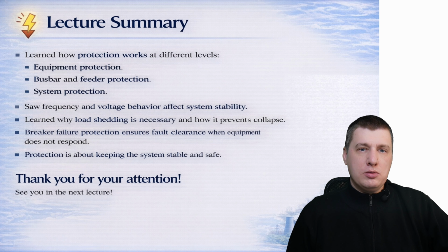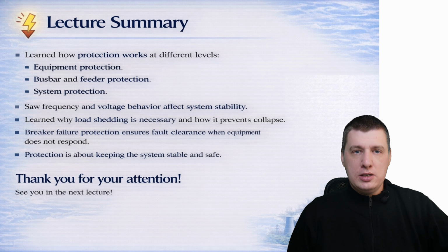We have reached the end of this lecture. You saw how frequency and voltage behavior affects system stability. You learned why load shedding is necessary and how to prevent collapse. You also learned how breaker failure protection ensures fault clearance when equipment does not respond. Protection is not only about tripping, it's about keeping the system stable and safe.